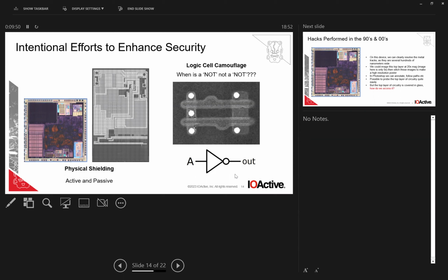Nowadays, you have much more complex devices, so they're much smaller, with many more layers of circuitry. Everything is encrypted pretty much now. If you buy a secure device now, it will have an encrypted ROM, the flash will be encrypted. Everything's encrypted, but at some point there has to be clear data on the chip. Very small devices, very sensitive transistors. You need to be careful when you probe the signal, you get almost nothing out of it, so you have to amplify it and condition it so you can actually make sense of it. But I've highlighted these top 2 points for a good reason.